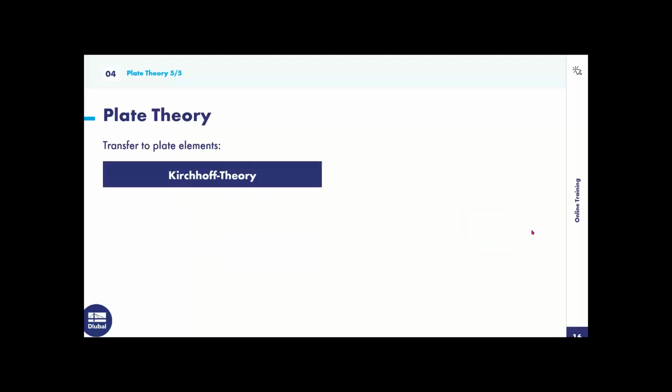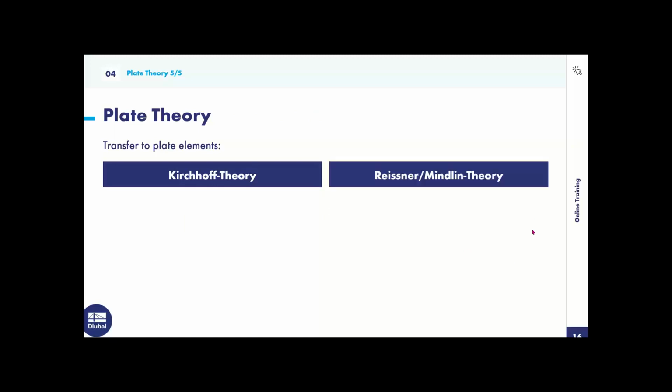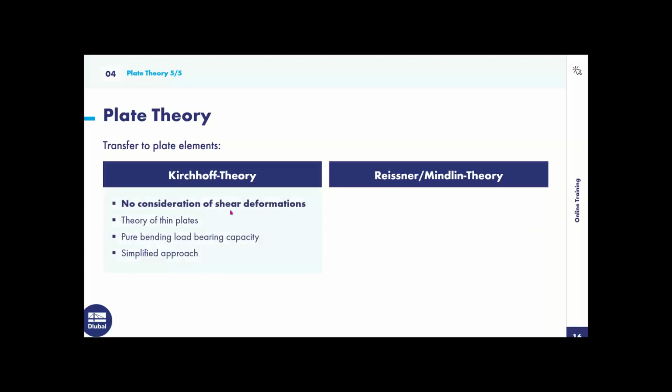Just to summarize, for the Kirchhoff theory and Reissner-Mindlin theory, Kirchhoff normally yields great results when very thin plates are used, for example, concrete slabs. You also have to keep in mind that this only considers pure bending load-bearing capacity, and this is basically a simplified approach.